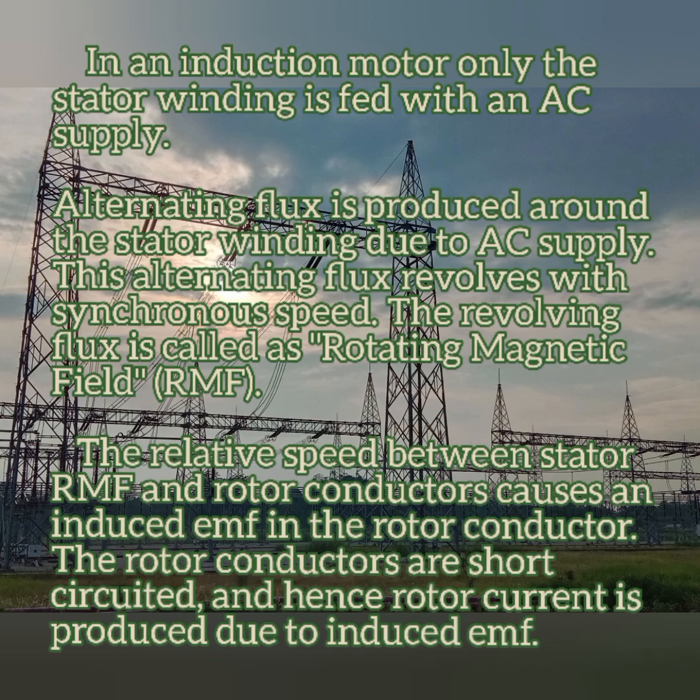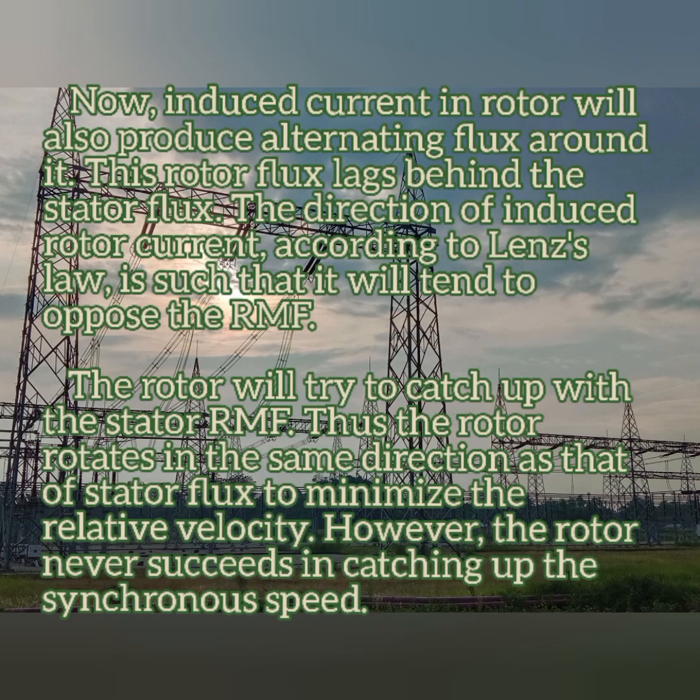So the relative speed between the stator RMF and the rotor conductor causes an induced EMF in the rotor conductor, and the rotor conductors are short circuited, and hence rotor current is produced, which induces an EMF in it. The induced EMF in the rotor will produce an alternating flux around it, and that flux will have some lag behind the stator flux.